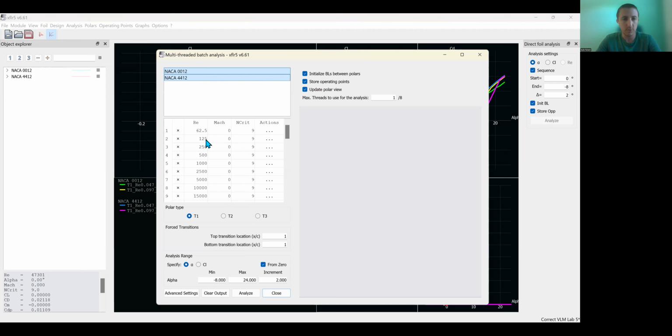It has a little issue with it being at 0 Reynolds number. Obviously, it doesn't exist, so it has an issue with that. But our Reynolds numbers will start from 47,000 to 97,000. But I made increments of 5,000 all the way up to 200,000. So way above, way below the actual Reynolds numbers that we need. And when you do that, it just allows it to interpolate the information and get to the Reynolds number you need when you do the wing analysis.